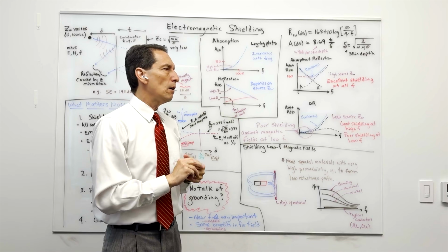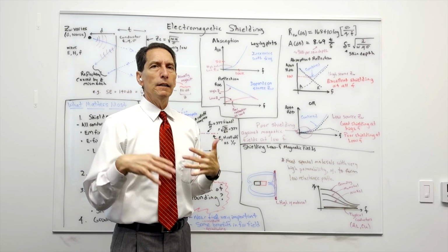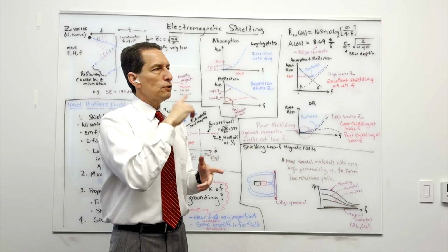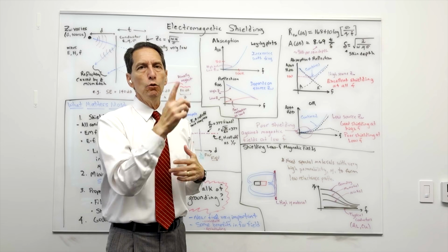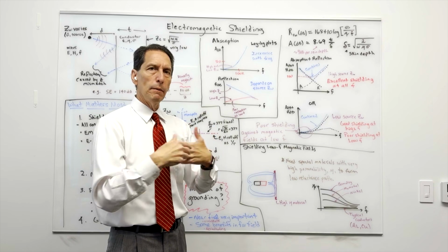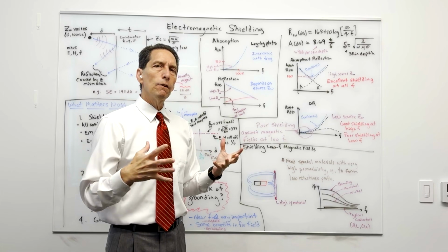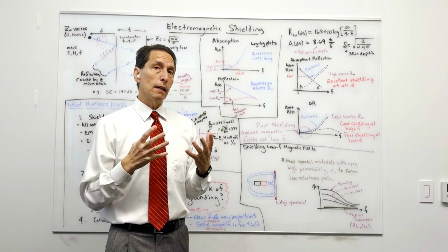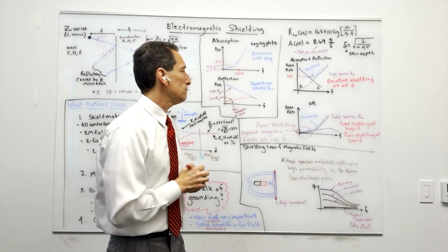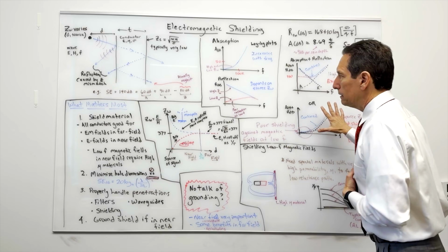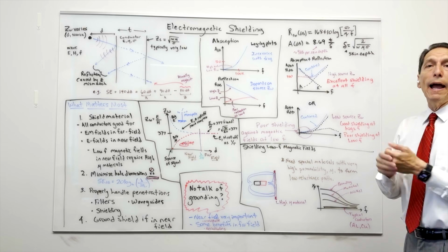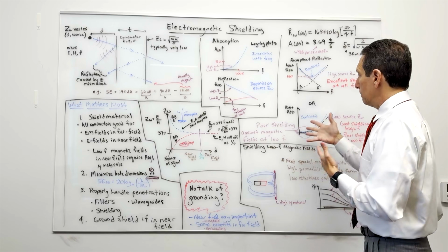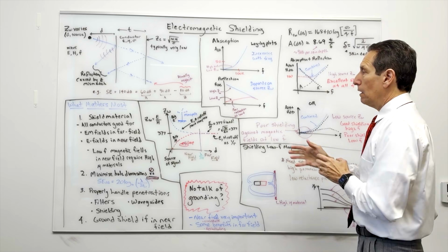And that's why it's so hard to block things like 60 hertz, that we use for our power, that's circulating around these wires in these big loops in our home and other places, and you generate these magnetic fields off of them. It's difficult to shield against those very low frequencies that are generated by magnetic loops, okay? Loop antennas. All right, so that's what that says. Now, how do you handle it then? Do you just give up and you can't shield against these type of fields?